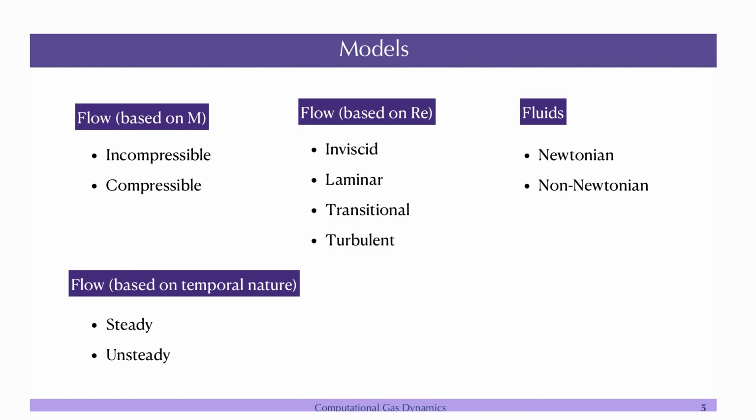And based on temporal nature, it can be steady or unsteady. In fact, even if the flow is steady, that means it can achieve a steady state solution, you start with, you do not basically discard the d by dt term, you still keep the d by dt term, but you make sure that d by dt goes to 0. That is what we do in the steady simulations.